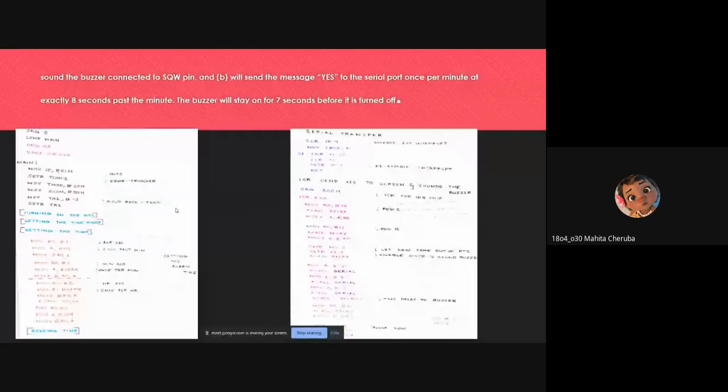So it follows for YES, and after everything we are again storing this in our register C's address. After that we clear the P1.7 port, and we return from the interrupt. The main things we have to note from this program is that we have to first enable the external hardware interrupt to make it edge triggered. So that is one thing we have to make a note of.